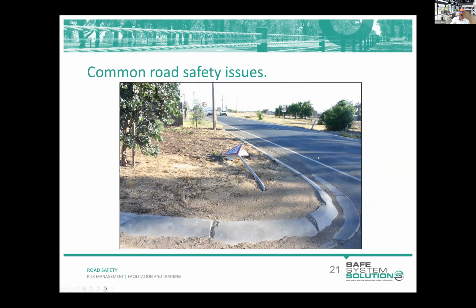So Jamie, sorry, one I missed in the Q&A. When you've got those conflicting vehicles in the intersection, overlapping swept paths and those sort of things, as an auditor, should you be checking the signal phasing plan as well to confirm that doesn't work, or do you just flag that and let them respond to that and deal with it?